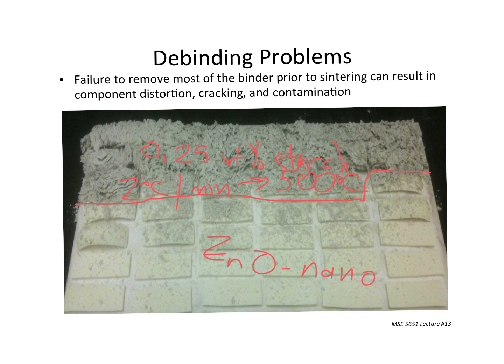These are the compaction forces being counteracted by the expansion and the force flow of the gases coming out of this pretty small amount of starch. This is way shy of what we're talking about for CIM or MIM, where it's like 25% organic. This is only 0.25% organic. So it shows you that if you don't control things correctly, and this heating rate is obviously too fast, and what we ended up doing in the rest of the lab was we stopped using starch because we could still make squares, rectangles that were suitable.